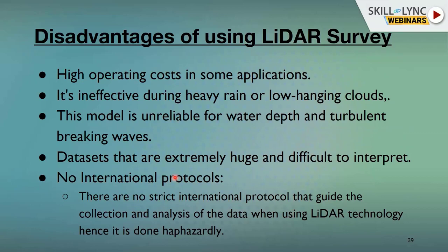The data sets are extremely huge and difficult to interpret. Yes, obviously, the data size will be in TBs. When I was working on LiDAR data in 2008, 2010, data handling, like uploading the data from the server once we were done with the work and uploading that data through FTP, was a very challenging part at the time. Now people are working very smartly, compressing the data size from GB to MB, like let's say 1 GB of data now comes in 100 MB. We can open that LAZ file format in any other software, like MicroStation or Rhinoceros in Civil 3D software.